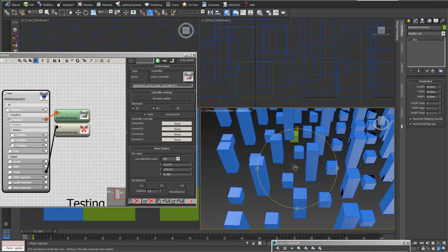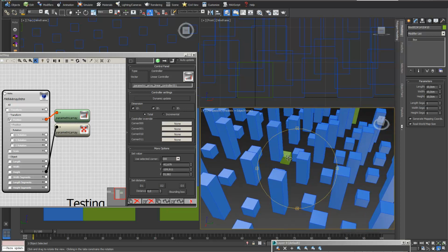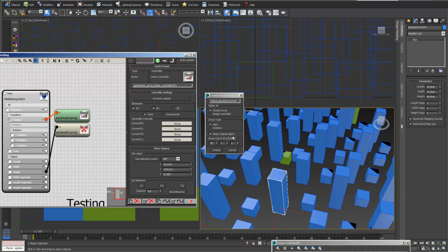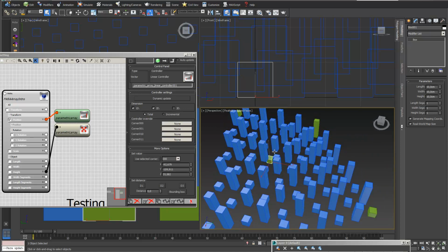And this little green cube is just a copy which we produce at the beginning when we open para3D. For example, if I choose this box and I go into para3D, we can see it's this thing, keep original copy, original object, and then the object number 1, box 001, is just there on top.